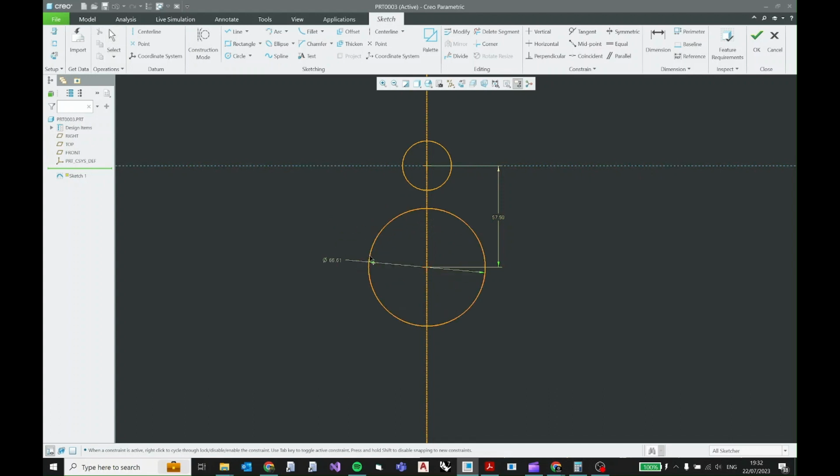Again, I'm able to change the diameter as well, so I'm going to press Control Z, undo this, and then make this and lock this dimension, so I won't be able to change it. Similar to this one, now we can see that the diameter is locked, but not this vertical distance. So I'm going to undo this and lock this dimension as well, so it is unchanged. If you try to click and drag it, it's not going to change.